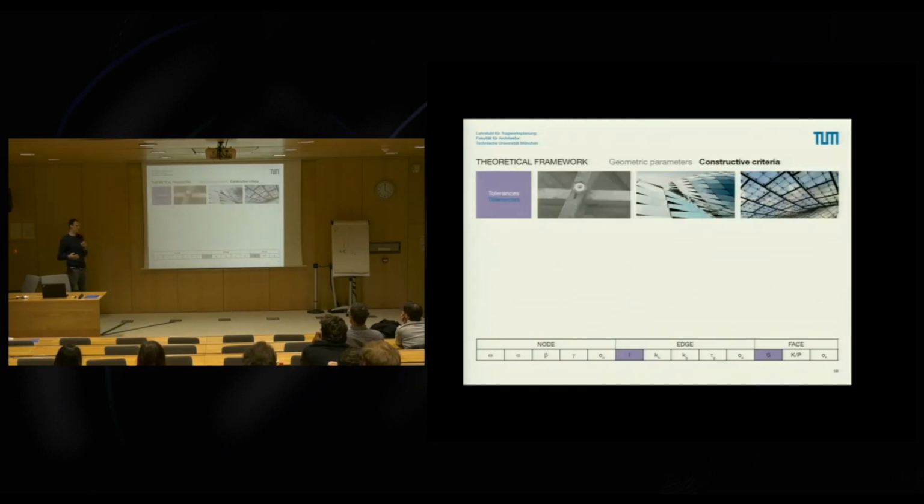The first one is very obvious, it's tolerances, right? Even though you might not have the same curvature in every panel, if you just have a little tolerance, you can make them all planar anyway. Or you can use the same size panels, which they did in the Olympic Stadium in Munich, by having a large neoprene gap in between them that serves as a tolerance to do so.